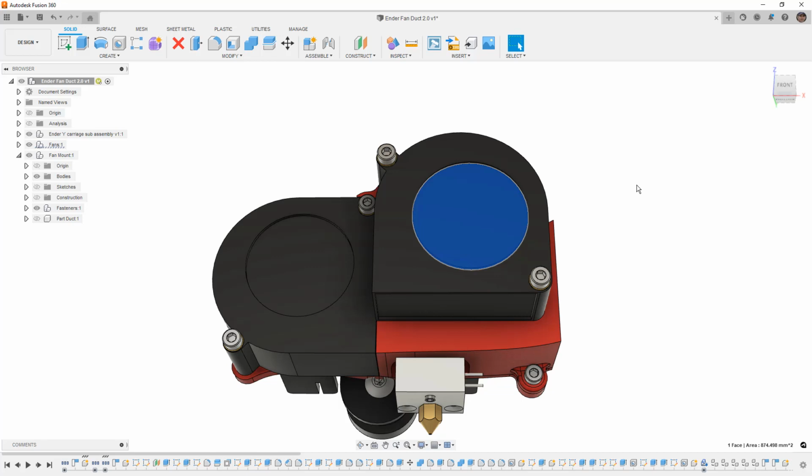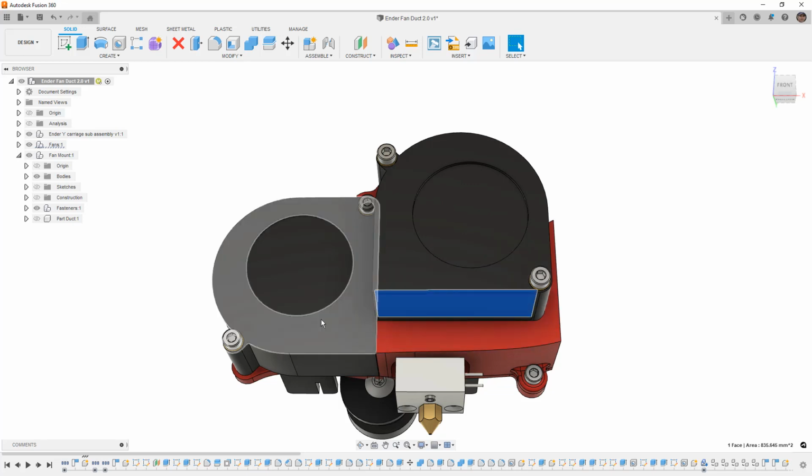The other thing that we really need to think about is that these fans are rotating and blowing out this big opening here. However, after about 50% of that opening, you have very much diminished returns. There's not really much going on over here, but we don't really want to just block it off. I have built fan cages before that rotate up inside the housing and duct out of a very small portion, and they do work pretty well. It really depends on the fan, and in this case, we don't have the profile of the blade or anything on the inside of it. So what we're going to be doing is working with this entire opening, but noting that we need to neck it down relatively quickly.